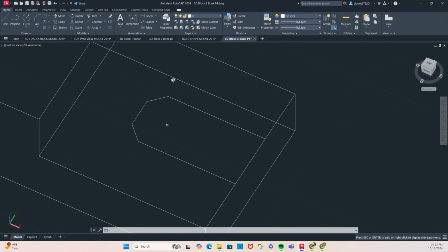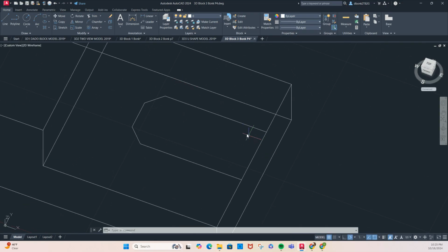All right, so let's see. I need to have a little line segment put in here also to complete this profile shape. Enter. And then remember, I'm going to do this join thing. Hit enter. In this case, what you want to do is make sure that you select just this line segment and click each of these individually to make sure that this works the right way, and then hit enter. And at that point, that's joined up.